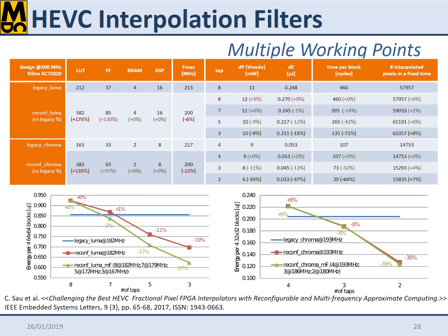Looking at the curves, the achievable trade-off allowed by our tap variable coarse-grained reconfigurable filter is clear. The comparison is against the legacy 8-tap filters for Luma and Chroma of the HEVC decoder. Reconfiguration involves high resources overhead, in terms of number of lookup tables and flip-flops, as well as reduction of the maximum operating frequency. However, our approach guarantees a trade-off in terms of energy consumption and image quality. You can clearly notice from the graphs that the reconfigurable filters, which are the red lines, consume more than the non-reconfigurable ones, look at the blue lines, only when the maximum precision is selected.